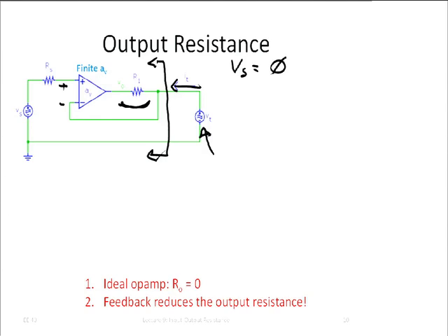Right? Is a voltage source linear? Yeah, a voltage source is a little bit special. If you went to signals and systems, it's very important to have an accurate definition of linearity. Linearity really means that the output is proportional to the input. Well, if you have a source, then the output is actually proportional to the input plus the value of that source. And that no longer follows that strict definition of linearity, and then superposition, for example, doesn't work anymore.